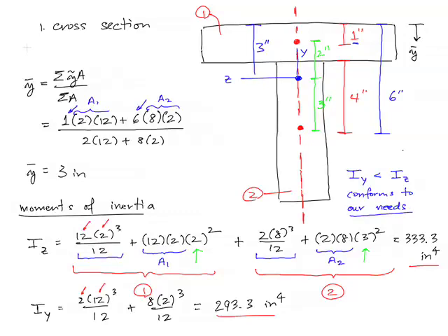And you can look at the book on page 323 for a description of this. Now, we talked about this in class a little bit. Basically, what this means is that we point the z-axis in the direction of maximum inertia. We point the y-axis in the direction of minimum inertia. So what that means is that the way we've defined the coordinates here with z and y are correct, and then that means we can get theta positive measured from positive z to positive y. So the way we've set up the problem is consistent with the way the book wants us to, so that the equations that are derived in the book are going to be useful to us. Okay, so that was an easy enough thing to do, and there was a small check we had to do there to make sure that we've got this all set up correctly.